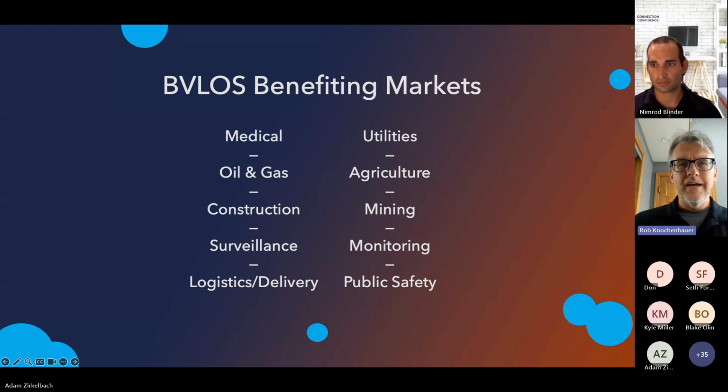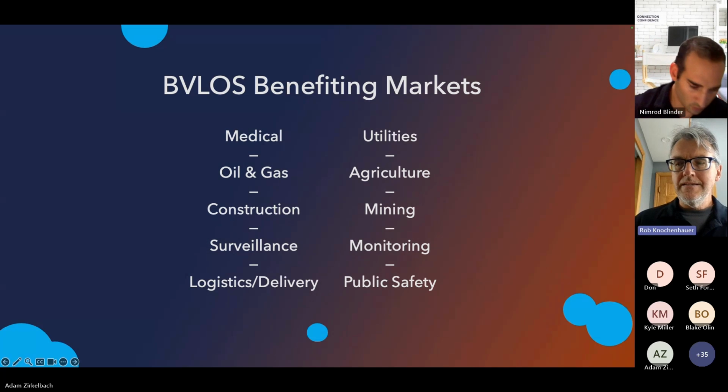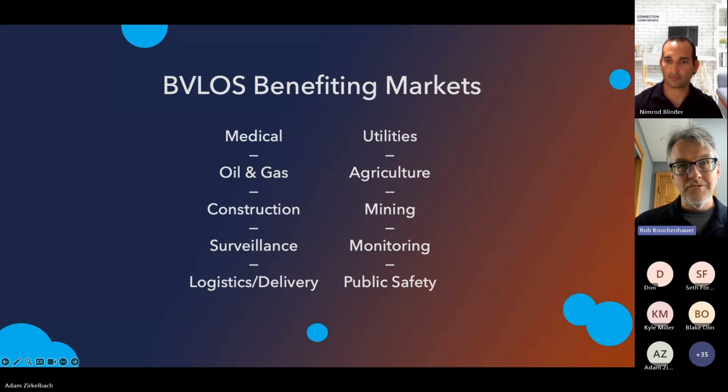So we have had approvals for running operations in controlled airspace, and in fact, an airfield where we do a lot of our checkout testing is in controlled airspace. It's a Class Delta, in Ormond Beach, where we were able to do both EVLOS and BVLOS operations, with visual observers and also leveraging low altitude shielding. That is part of our safety case, where the performance-based requirements that we've put forward allow us to do operations in any controlled airspace. The restrictions become the proximity to the airfield.